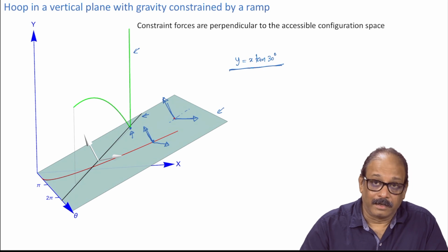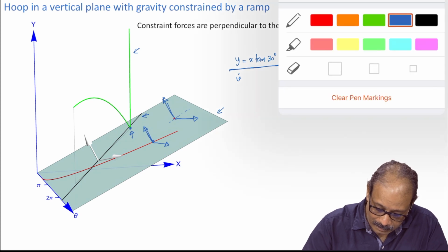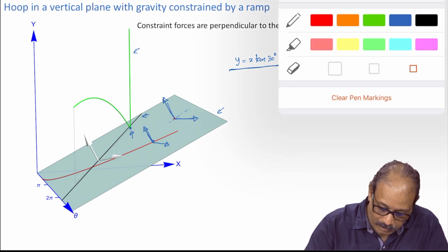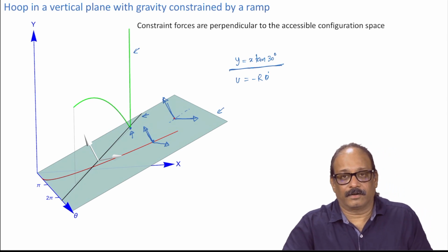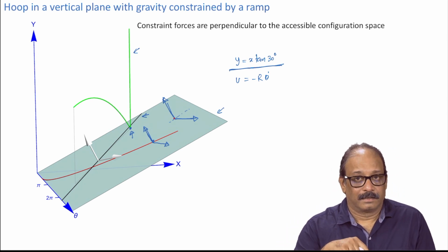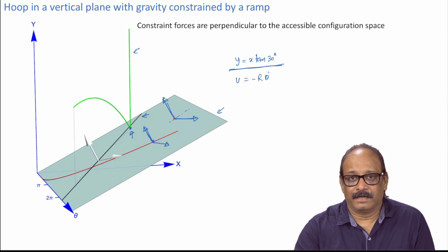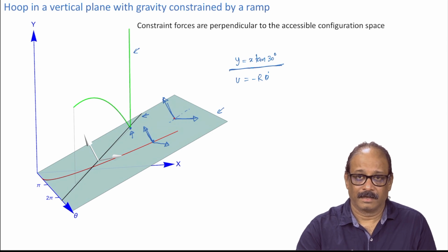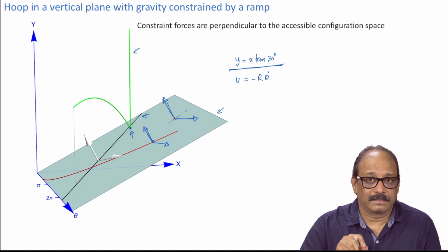Okay. Whereas, a third case is the black trajectories where the motion is rolling without slip or without sliding. What happens? Now, you have a constraint, and what is that constraint? Velocity or speed is r theta dot. This constraint, remember, in this case is integrable and hence it is actually a holonomic constraint. So, and this constraint is enforced by which force? That is the frictional force.